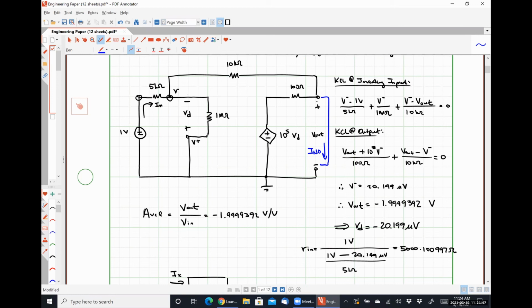So let's look at this first equation here, right? Vout is now defined to be the voltage drop over that short circuit. So what does Vout have to be? 0 volts. So that means we have one equation, one unknown, in which we can find our voltage V minus. And then we can do Kirchhoff's current law at our output node, saying this current in plus this current in is equal to I Norton, and we're good to go.